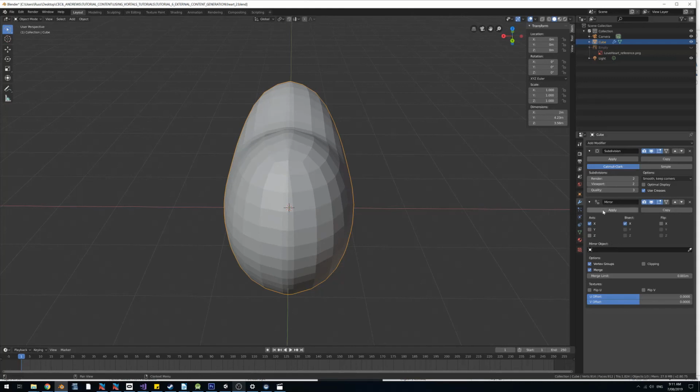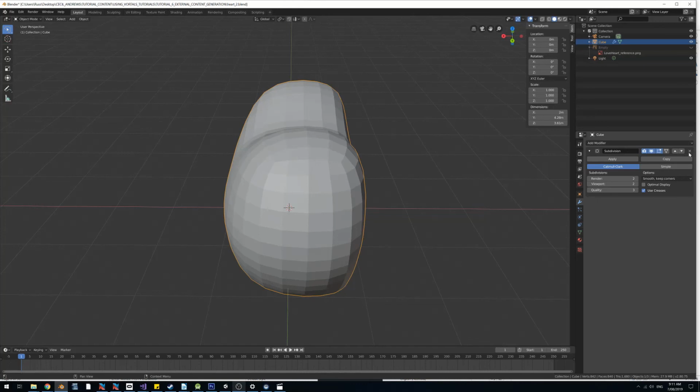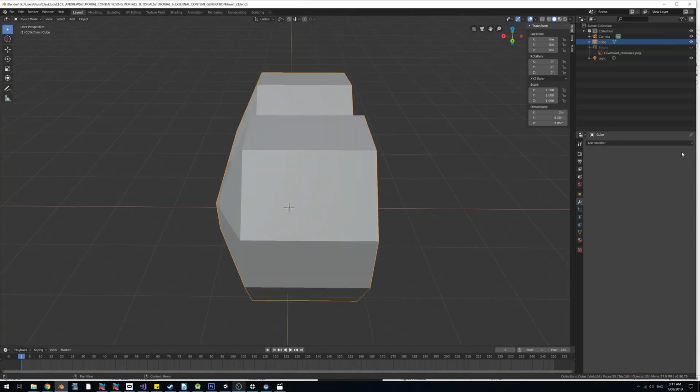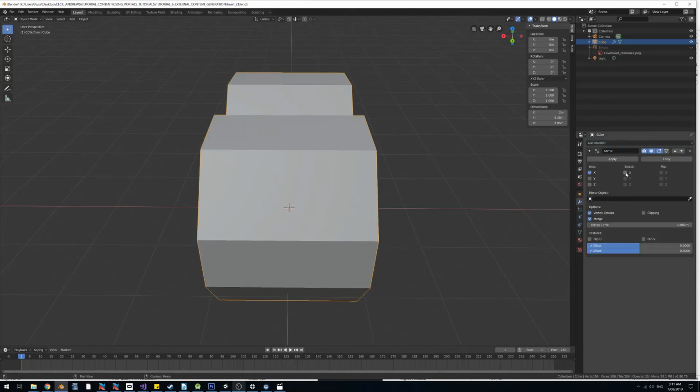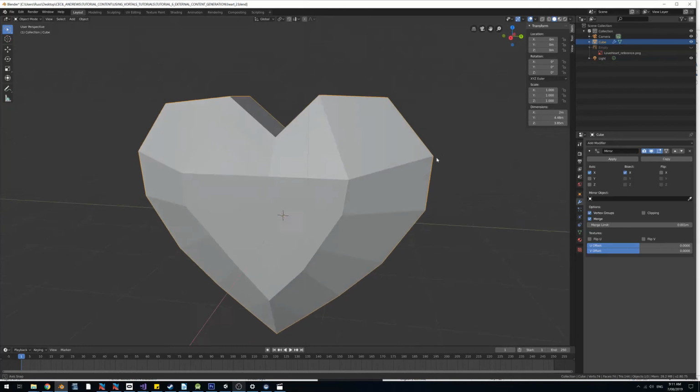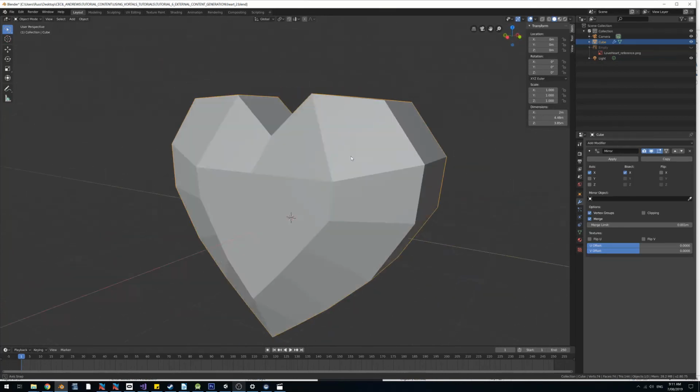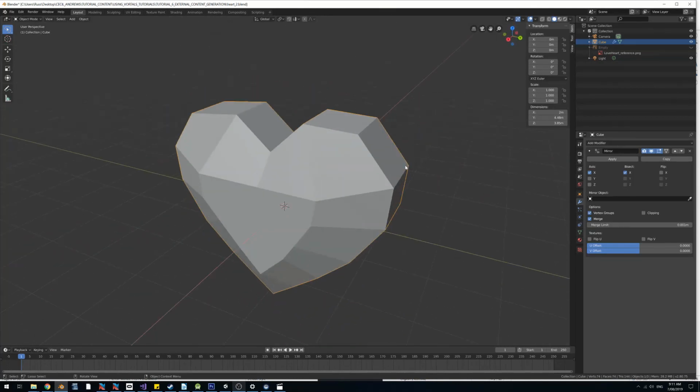We could, however, apply a mirror and then do the smoothing. And in this case, that will make a very big difference. So let me delete, by pressing the X button up here, both of these modifiers. And this time reapply the same modifiers, but in a different order. So now I'm mirroring the heart before I apply a smooth. So here we have the result of that operation.